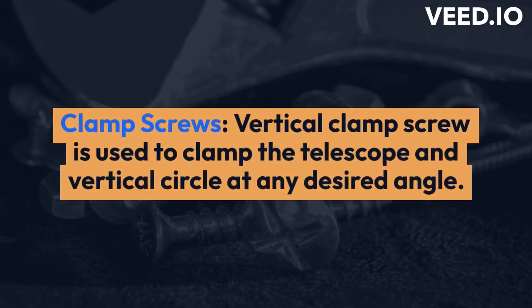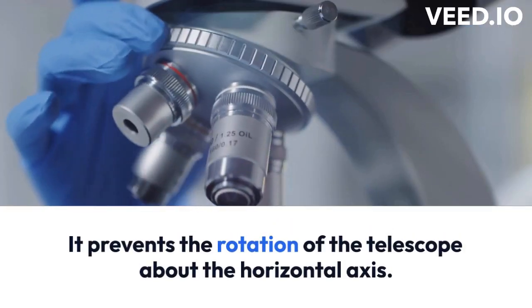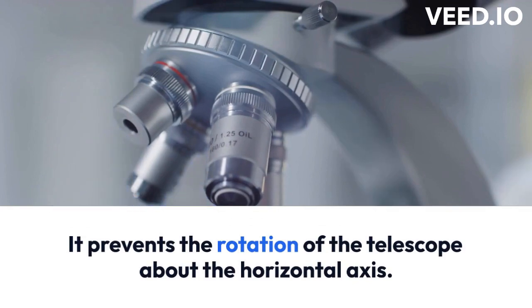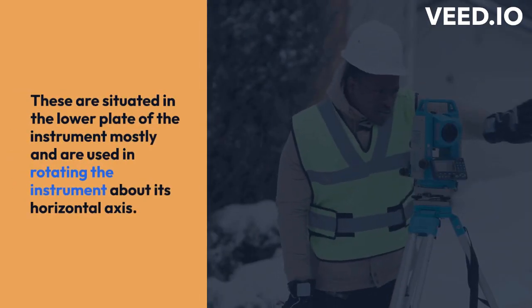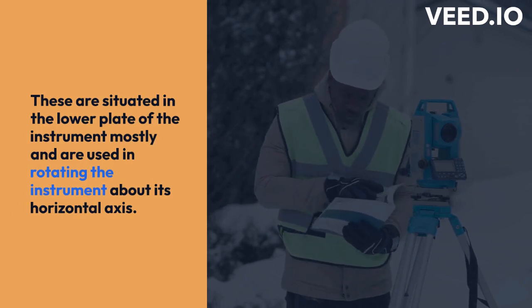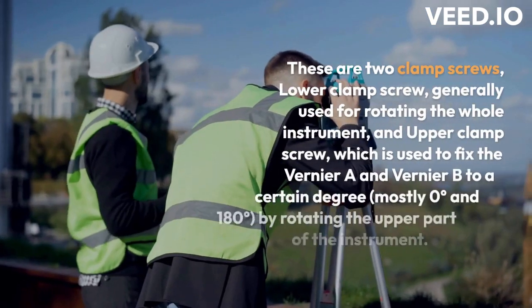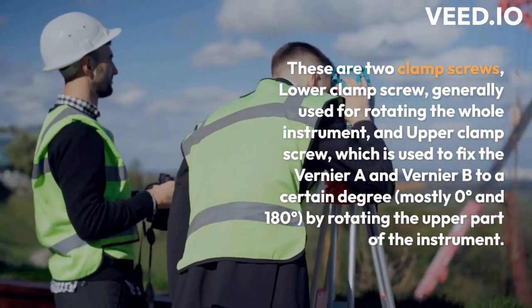These are situated in the lower plate of the instrument mostly, and are used in rotating the instrument about its horizontal axis. These are 2 clamp screws. The lower clamp screw is generally used for rotating the whole instrument, and the upper clamp screw is used to fix vernier A and vernier B to a certain degree, mostly 0 deg and 180 deg, by rotating the upper part of the instrument.